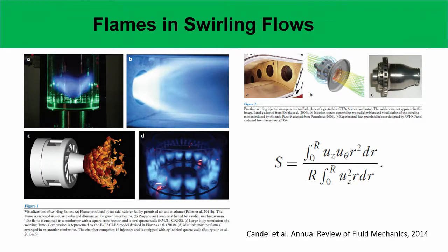the different kinds of flames in the primary zone should look like, because in the primary zone what you have is the liquid fuel injector, and the liquid fuel injector is surrounded with the swirl blades, okay, which provide the tangential momentum onto the otherwise axial flow. Okay. Now, why do you need this tangential momentum?